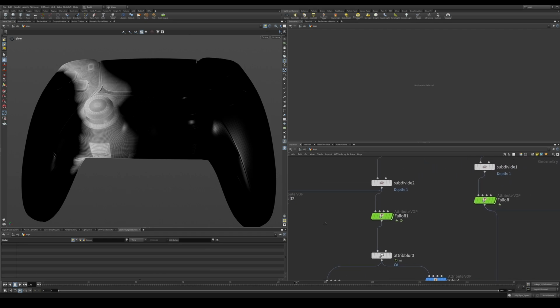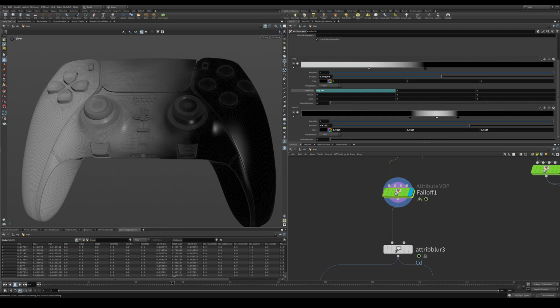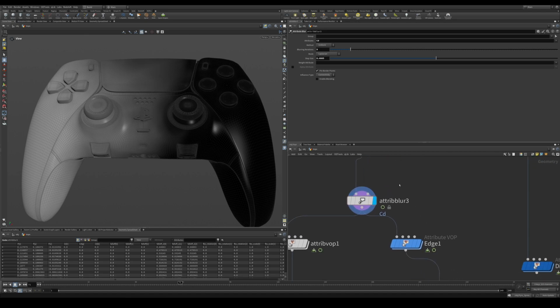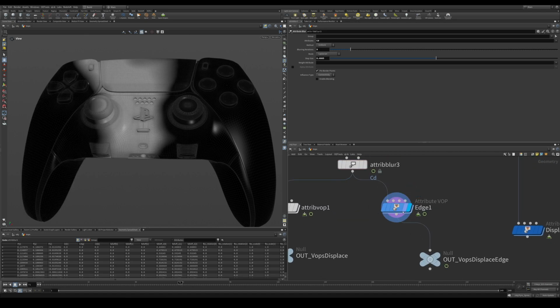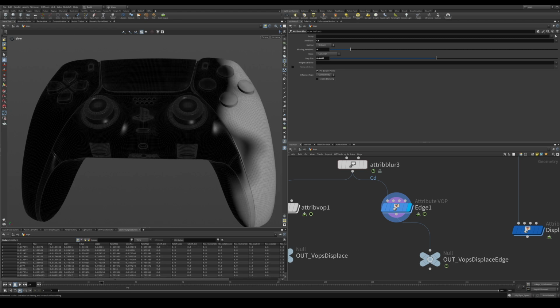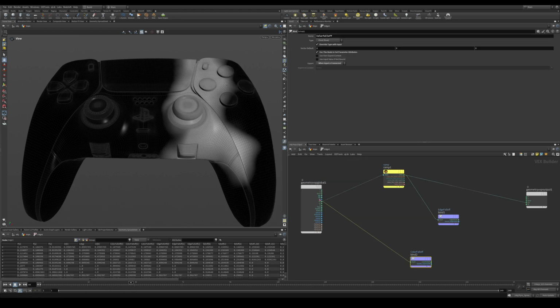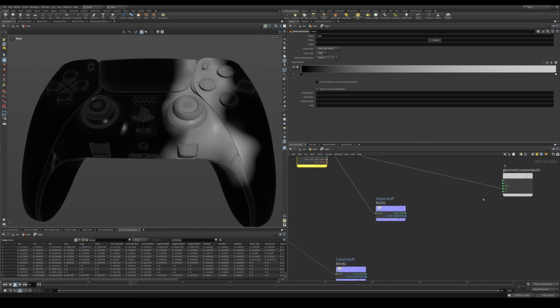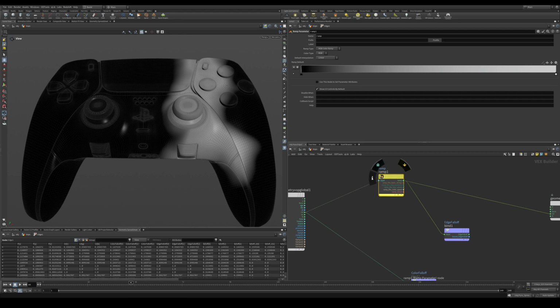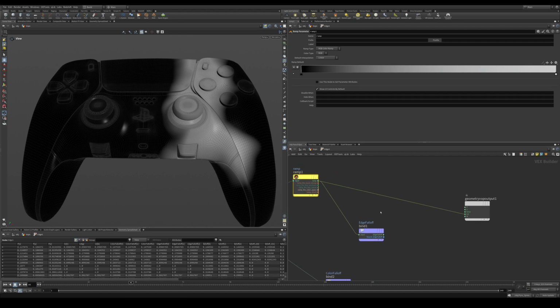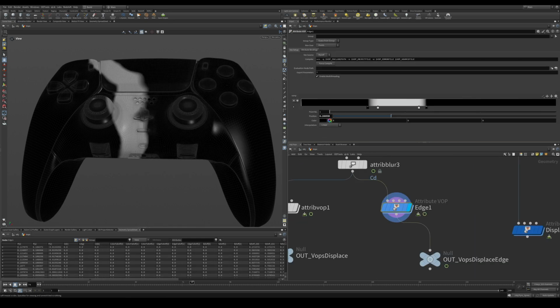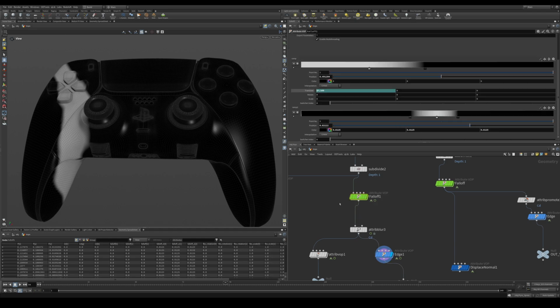And so we'll just keep moving forward here. So this is our original fall off, and then we have our settings here. We got all of our different things, and we got the attribute blur, which is blurring color, and then in here we have a remap of this effect here. What we do here is we get the color, and then we get the ramp, and then we put it back to Cd. So connect Cd to the ramp and back out to Cd. And then you could put a bind export to get the different attributes there. So as you can see, it still follows the original animation from this setup.